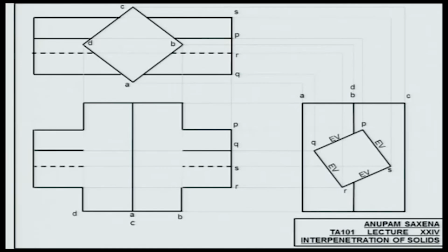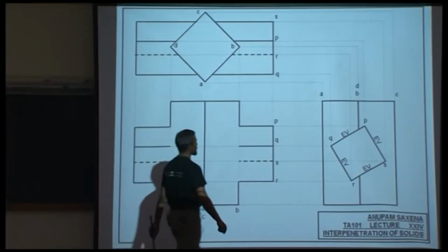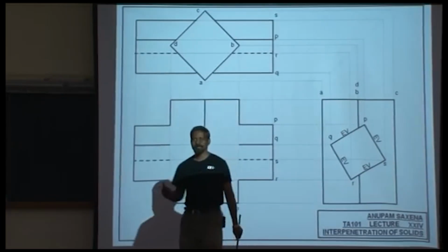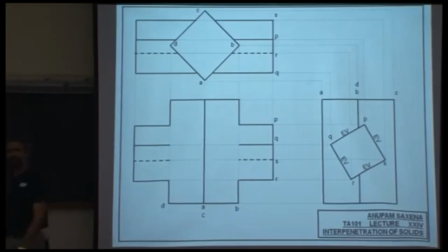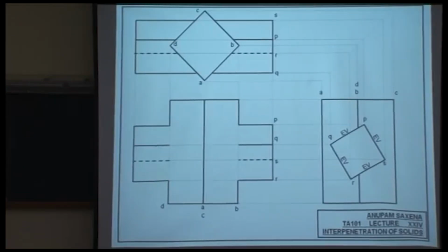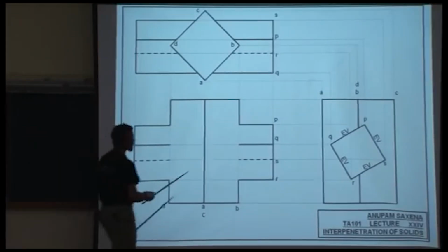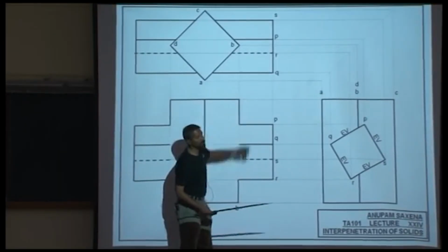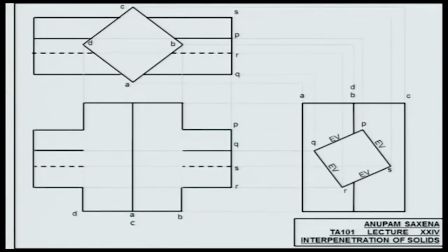The labels happen to be the same. PQ, QR, RS and PS, they all happen to appear in the edge view, in the profile view. Okay? So it's kind of obvious for me to extract the intersection point information from the profile view. Having said that, now of course, when I rotate this horizontal prism PQRS, the corresponding projections in the front view and the top view will change. Now, okay. First intersection point.